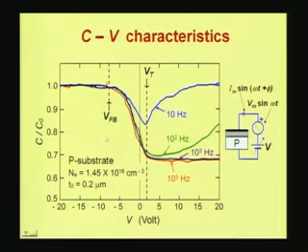So we would like to explain this variation in the capacitance as a function of voltage and also as a function of frequency, and then we would like to derive formulae for the VFB, that is the flat band voltage, and Vt, the threshold voltage. Now let us explain what is meant by this C0 capacitance, which is used for normalizing the capacitance of the device.